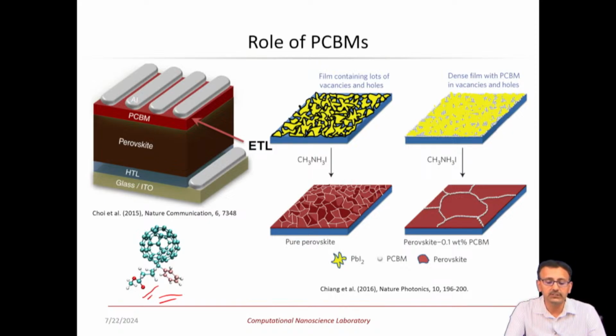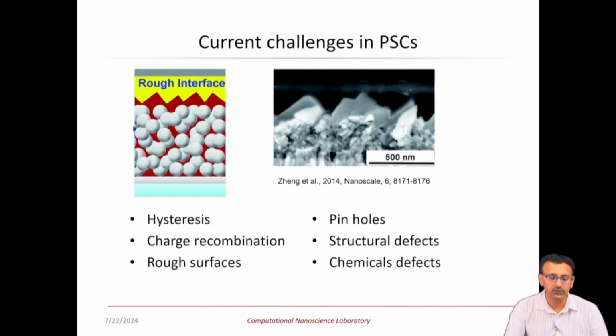If you add this to the solvent, then some of it gets incorporated in the grain boundaries of the layer that forms this perovskite layer, and that is able to mitigate the impact of some of the common defects such as lead iodine anti-site defects. They are able to bind with the iodine, and that reduces recombination of electron holes when they are transported through these films.